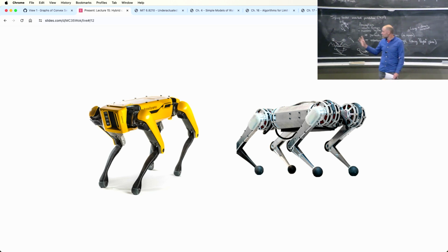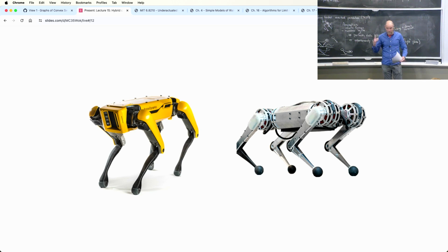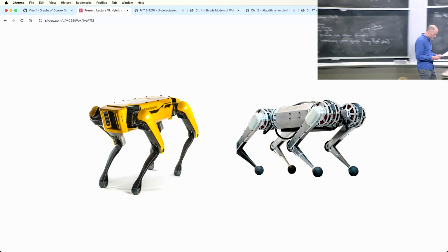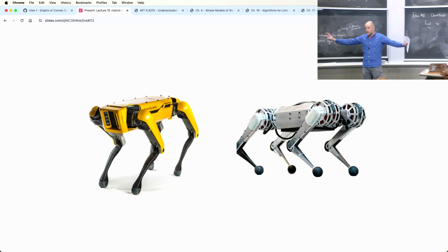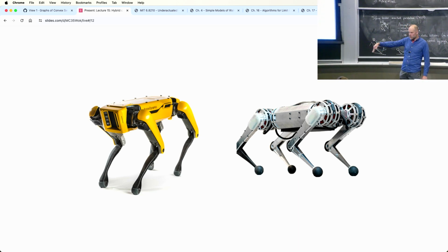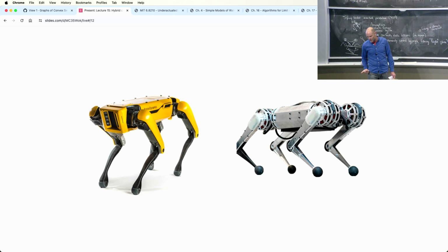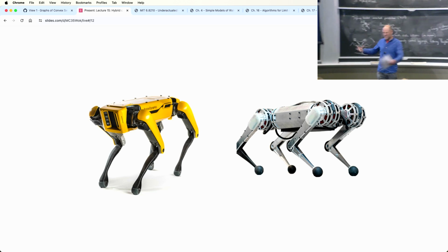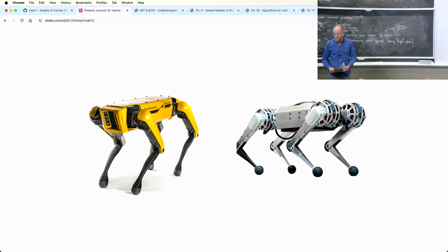So actually, a lot of the revolution in quadrupeds is when we started building these actuators mostly up in the body, with super light distal legs. Do they pad the body with extra mass? The Raybert hoppers very explicitly did, right? I think a quadruped already has an elongated torso. What matters is your inertia relative to the leg: you want the assumption that when you move your leg, your body doesn't move much. So if your hip is a pin joint about the y-axis, you want the inertia around that axis to be big. Quadrupeds naturally have that. The Raybert hopper had a boom, with the weights off to the side, to make that assumption good.